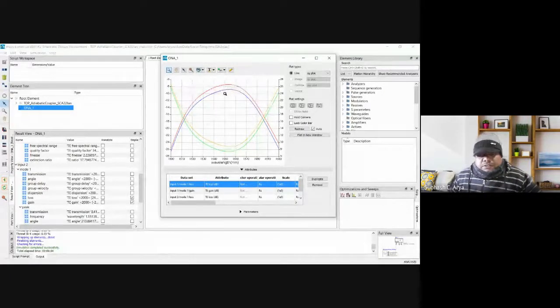Now this is the loss one. So loss is visible at 50-50, but the power splitting is not exactly 50-50. That I want to say, because if it is 50-50, some gap is there, but more or less following the same path. So this is the adiabatic grating coupler.